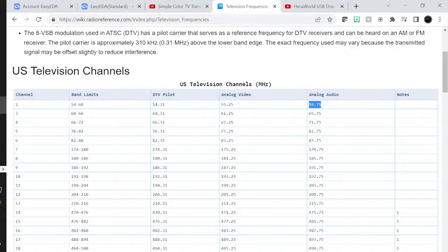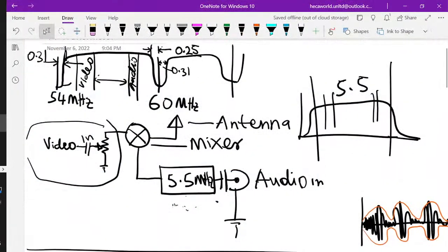I just have one amplitude modulated and one frequency modulated. The frequency modulated will be your audio, and the amplitude modulated will be your video. And then once you tune your TV to channel 2, it is capable of receiving this duplex transmission, right? But you can use one transmitter to achieve that by building it in this way.